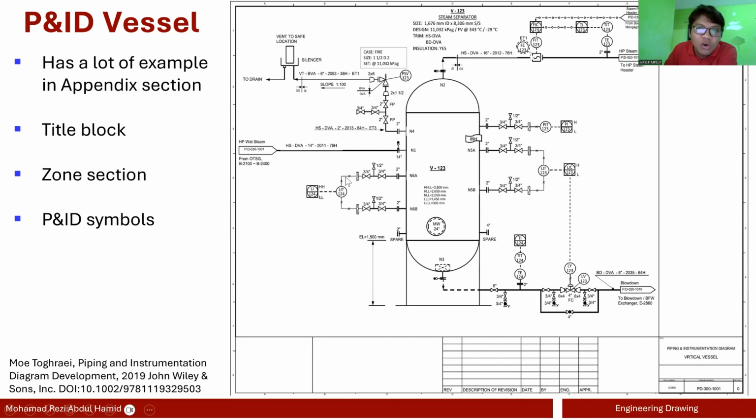If you refer to your symbols, this line and then dot is a capillary tube signal line, so you should know what this means. It will measure level. LIT is a level indicator transmitter to indicate the level of a liquid in the vessel. So the liquid goes here, liquid goes here. They will check the level, and these are capillary tubing, by the way, and then the transmitter will send a signal to the level indicator. This symbol is at the DCS, your distributed control system.